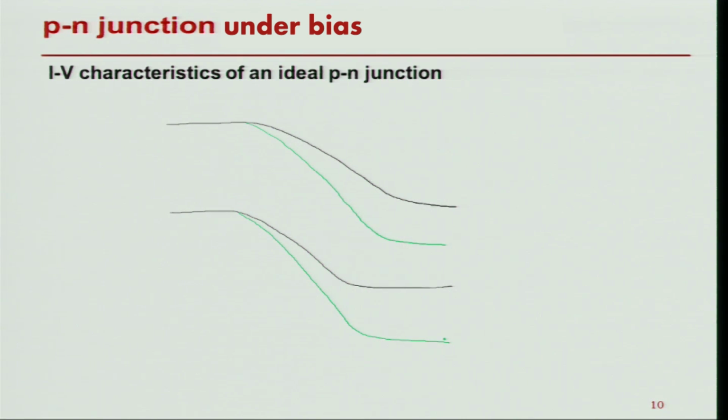Now, what is that doing? It is effectively again in these 3 regions that I can plot. Whatever little bit of diffusion current I had in the beginning due to the holes here, now even those will not be able to find enough energy to surmount the barrier and go to the P side. They will all be reflected back because of this higher potential. The potential now has changed from VBI to VBI plus VA. So, the diffusion current is considerably reduced in this case.